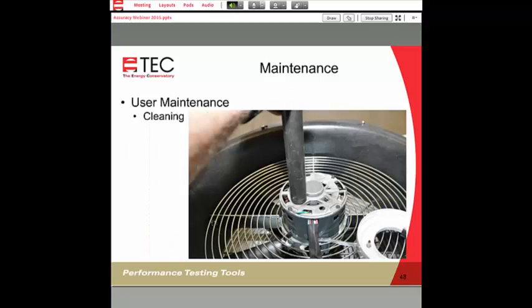For cleaning, we see this occasionally when a fan has a problem where it periodically shuts down all by itself. When it shuts off by itself, it tends to mean that the temperature sensor inside has been tripped and turns the motor off to cool it. When the temperature has gone down, the fan will start back up again.